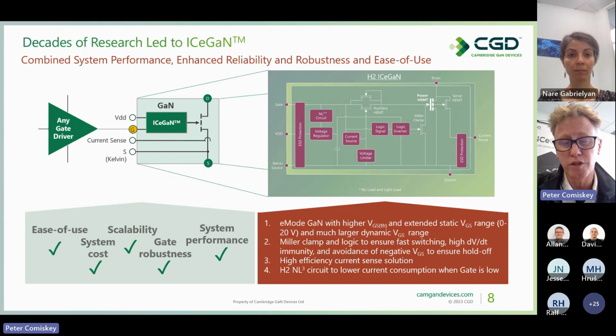One point to highlight here is from a thermal interface perspective, GaN has its thermal interface down to source, not up to the drain, as you would find on a MOSFET. So from a thermal perspective, what we try to do in our application is have a really low impedance connection between source and the ground layer in your application.